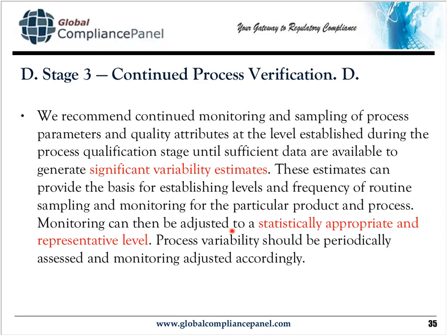Make sure your monitoring is adjusted to a statistically appropriate and representative level. Again, if your statistics are showing you that there's very little variation induced due to a step, then your monitoring of that step does not need to be as rigorous. And it's the steps in the process that give you the variation. Those are the ones that you really need to look at. You need to look at it with a sufficient number of replicates.